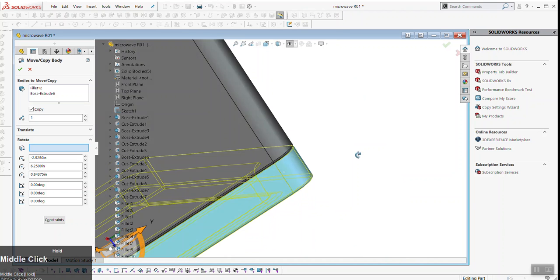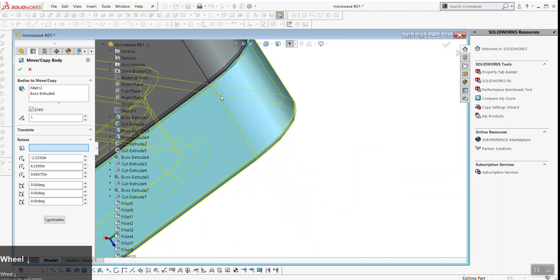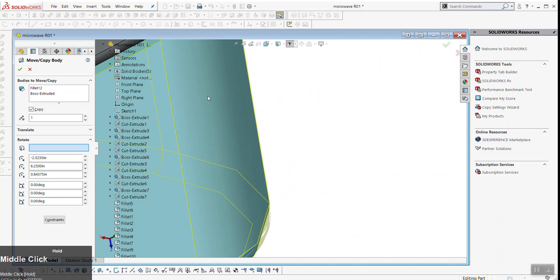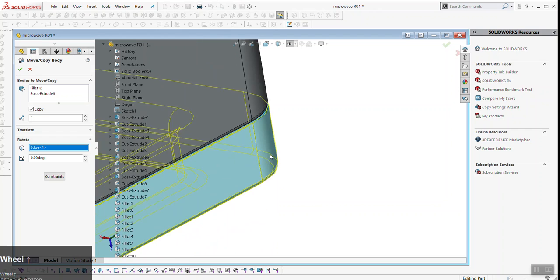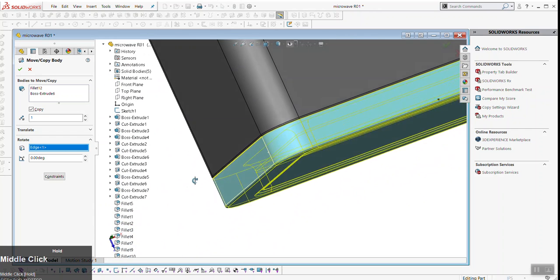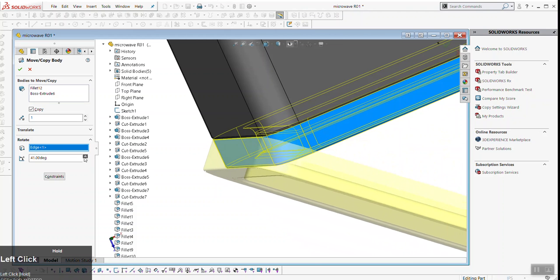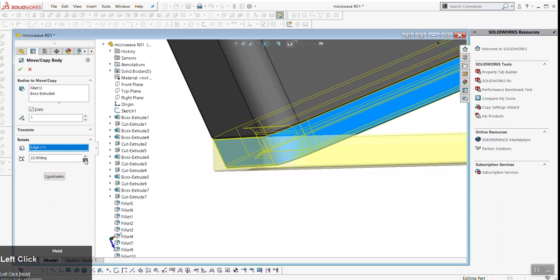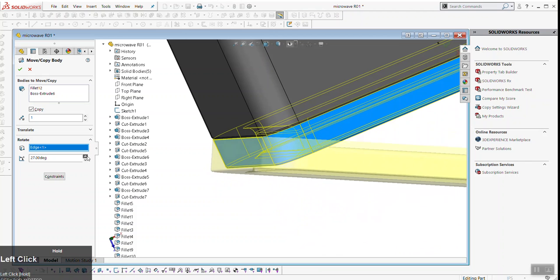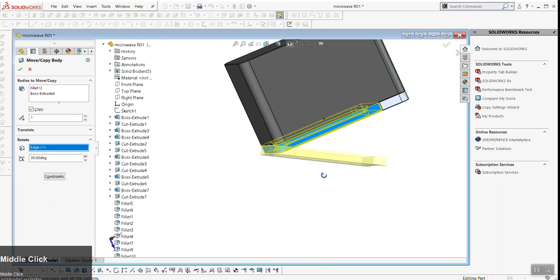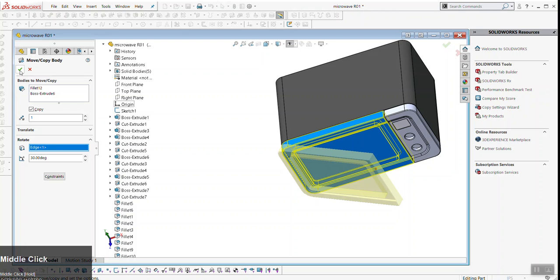If I'm feeling lazy and I'm just trying to get a rendering and I don't think the client's going to notice if this is a little off center, I can just select this edge here. For this class, if you want to do that, you can select this outside edge. You'll notice all the options disappeared on the left here. Now there's an angle in degrees. As I hold on these arrows, I can move this door a calculated degree amount. Let's say I want to open 30 degrees.